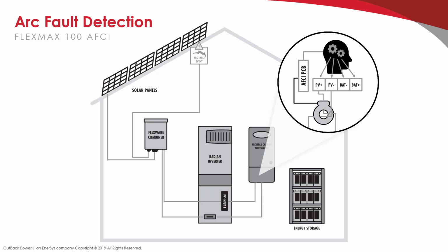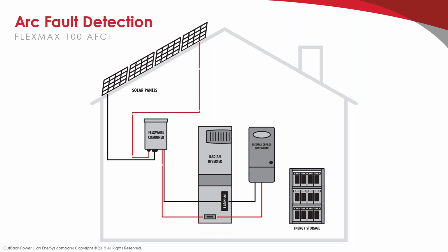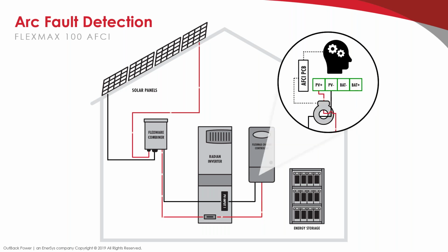And you wouldn't want to do that until you determine the cause of the arc fault event. So understanding where the arc occurred, basically doing a standard arc fault detection procedure along the PV array before powering it back on. So once the arc fault cause is determined and fixed, then you'd start it back up, and of course the power would start flowing again immediately. The charge controller will clear its arc fault event, and the operation can proceed.